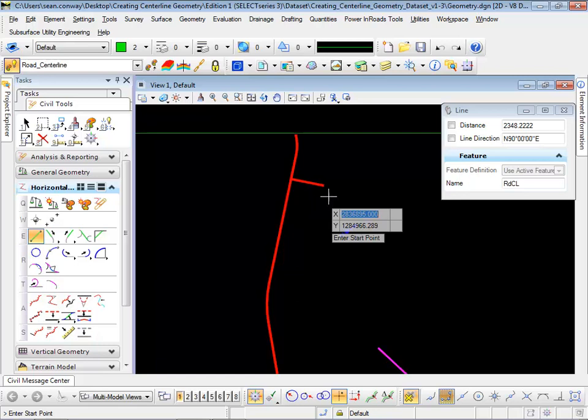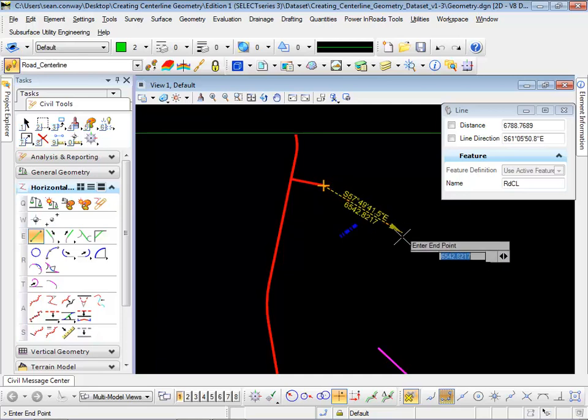We're going to continue from here, but we're going to disable Civil AccuDraw and just use the commands on the geometry dialog or the geometry prompts. So I'll toggle off Civil AccuDraw, and we're going to place another line between points coming off of that previous tangent. So I'm going to snap to the east end of that line that I just created. So my AccuSnap was present there. I saw a yellow X, and I just left clicked on that to snap to the end of the line.